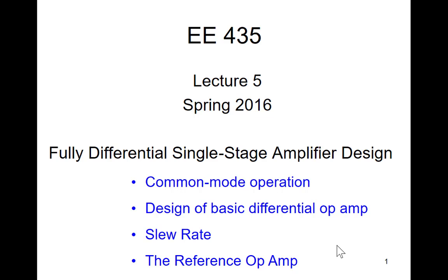But I did observe a couple of things going on that concerned me a bit in regard to your use of the test equipment. Oscilloscopes are very useful, and every waveform that you look at, you should be monitoring it on an oscilloscope. Triggers on oscilloscopes are important because they can make the waveform sit still instead of run across the screen. And I saw some issues with people not taking advantage of the triggers on the scopes. So hopefully when you go back and repeat this measurement, if you're not already doing it, you'll also come up to speed again on doing a trigger on the scope. Okay.